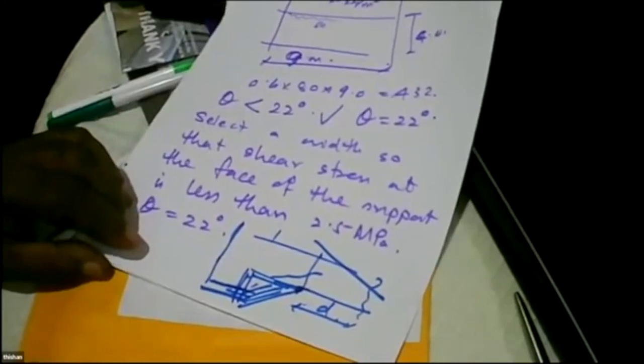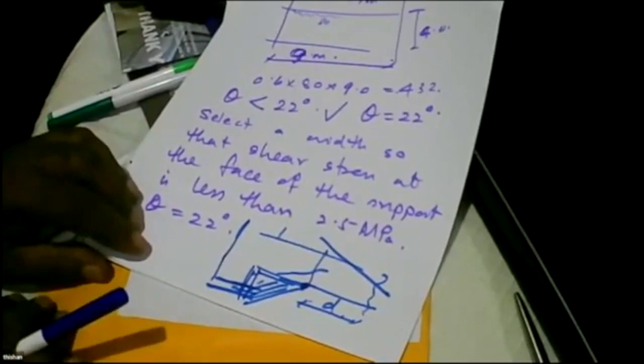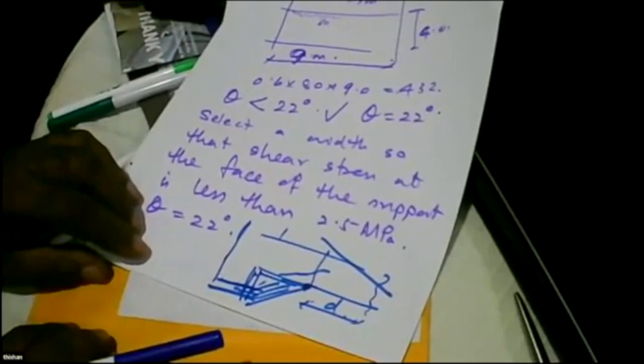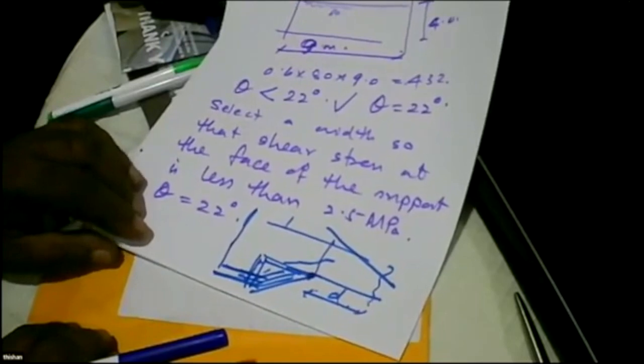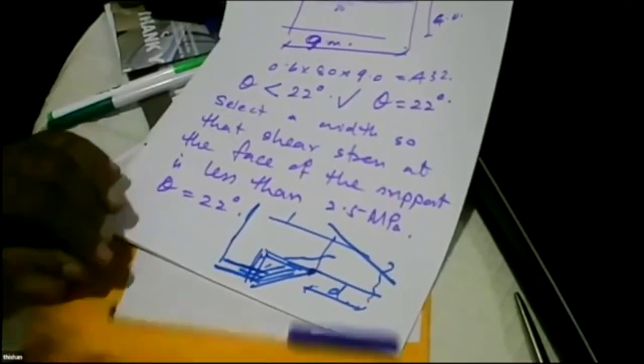Could you understand the method, Bandhu? Yes, sir. That is clear. Very simple, because shear failure always occurs D away from the surface of the support. So you change the phase of the shear by having a steel bracket. Got it? Got it, sir. Yes, sir.